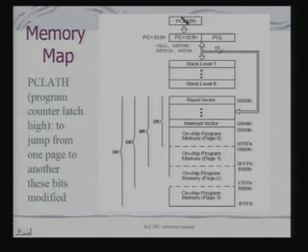This part is mapped to the program counter latch high register, and it is connected as per the architecture. Also, you remember it is connected to the hardware stack, and through the 13-bit bus it is connected to the register bank as well. What I have shown are the individual pages, which are of size 2K. And the first page typically has your reset vector and interrupt vectors.